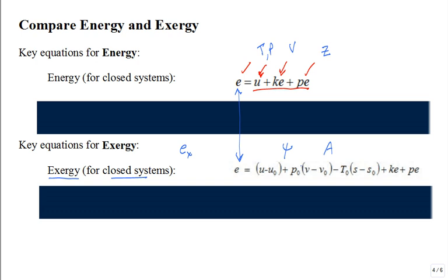All right? Okay. Now, what is U? Is that the same U? Yes. All right. What is this V right here? Specific volume. So if I said, give me the specific volume of water at a temperature of 300 degrees C and a pressure of 200 kilopascal, do you think you could go and get that specific volume? Sure could. Oh, it may be superheated water. It may be subcooled liquid. It may be two-phase something, but two independent properties fix the state. I was able to get U and V.